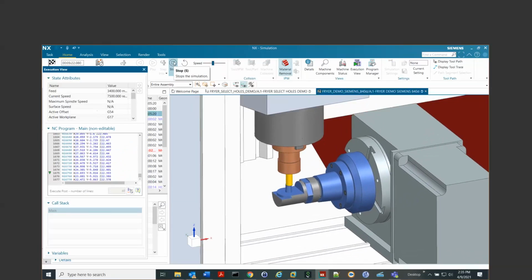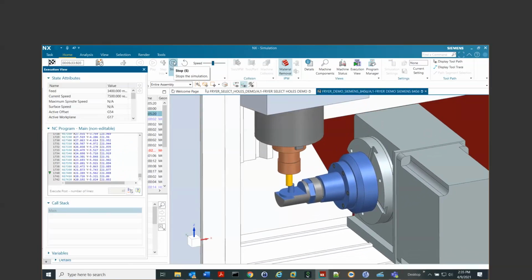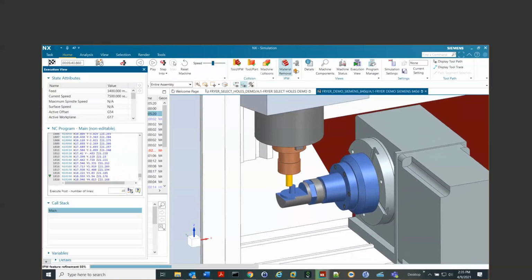So right here, this is what we call pillar machining. The pillar is what's left over from doing the bottom up adaptive milling. We have two choices within our program for machining that pillar. If it's a low pillar, not that much height to it, I might choose to leave it in the adaptive milling mode.